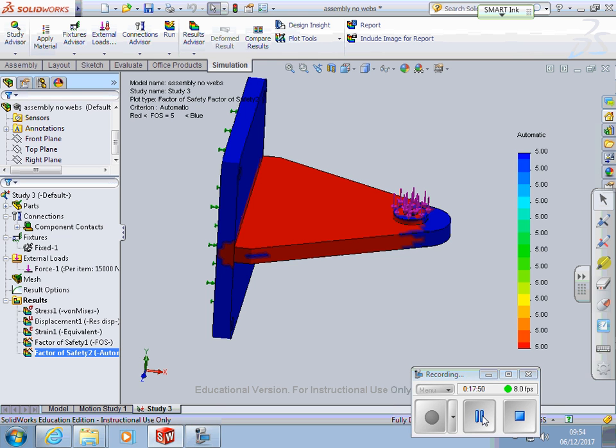Not that I know of. No. You're looking at setting up or changing the load and running the analysis again. So, the way I'd probably go about doing that is the old half-it rule. So you go down to 7,500. If that's all okay, then you go halfway between the two, and you're kind of halving the problem all the time. But I'm not looking for you to go down to the nearest Newton. Okay?